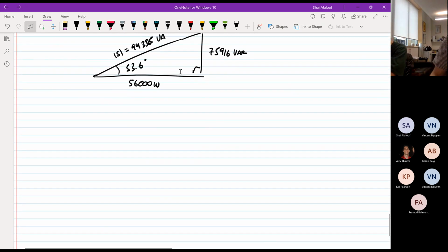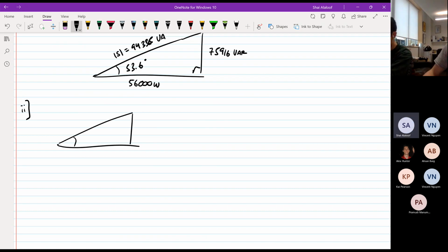Again, with the power factor correction questions, I think it helps if you draw the new power triangle. If you do cos inverse of 0.8, you get approximately 36.9. You're assuming that the average power doesn't change since you're adding a capacitor, which only consumes reactive power.